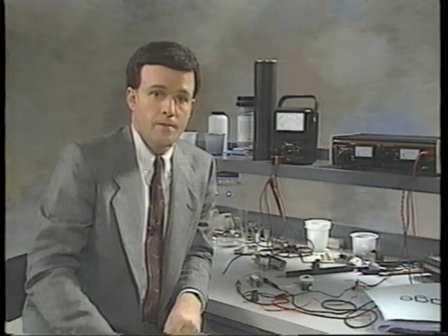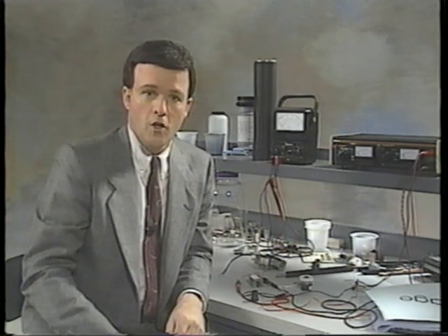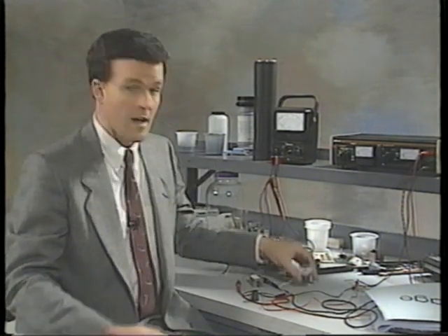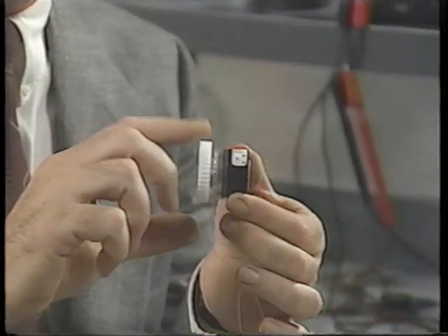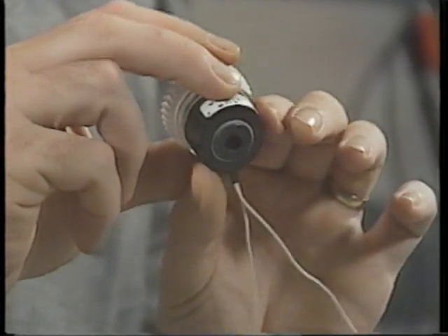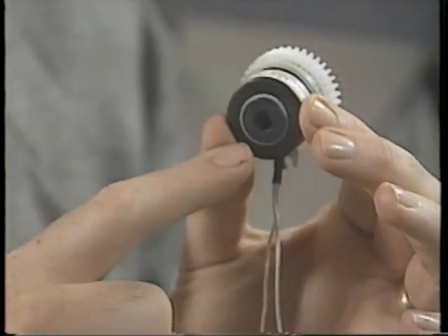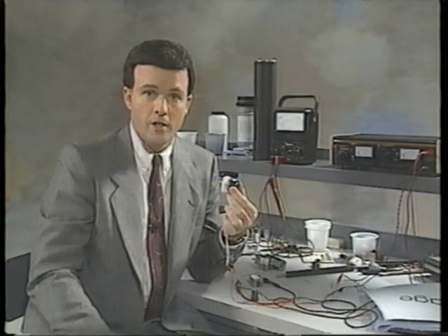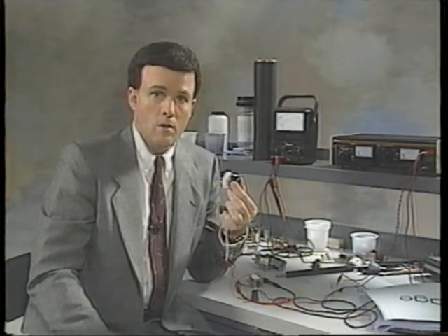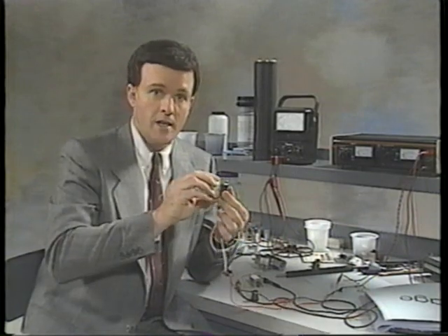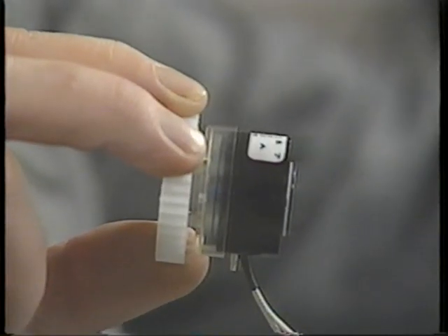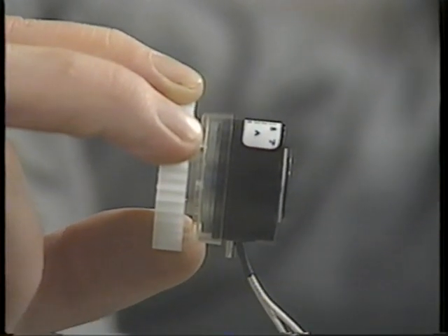There's another type of clutch that's sort of a clutch and solenoid in one unit, a magnetic clutch. It uses two plates, one driven and one idle, something like the clutch in a car. To activate a roller, the copier energizes the electromagnet, which pulls the two plates together.